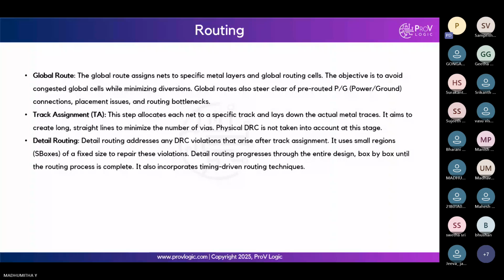Next is routing. This is the final design stage of routing. After routing, everything that we are going to do is only the testing and checking part, like timing analysis, final verification. All of these are the checks that we are going to do on our design. Routing is the final stage where we are completing the design. So the design part is over by routing.